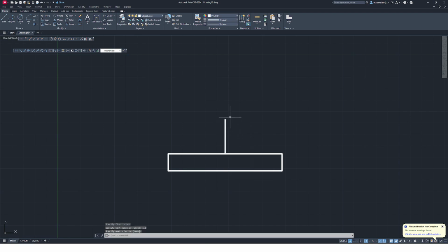Now, this thing is also 1.5 wide, so we got to offset half of 1.5 in each direction. Half of 1.5 is 0.75, so 0.75. Now, we're going to go across the top with a line. Okay. Now, this thing has a radius of 0.75. That gives us this. So I'm going to offset this 0.75 as well. It's already set to 0.75, so I will do a line here. I can erase this one now, and that's my front view.